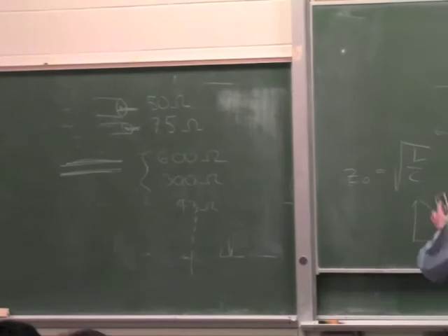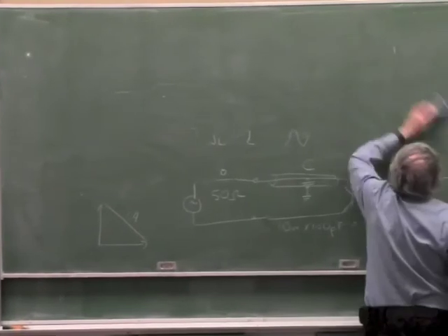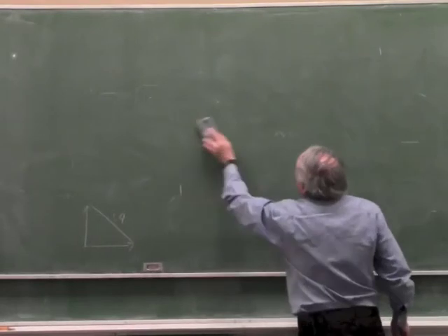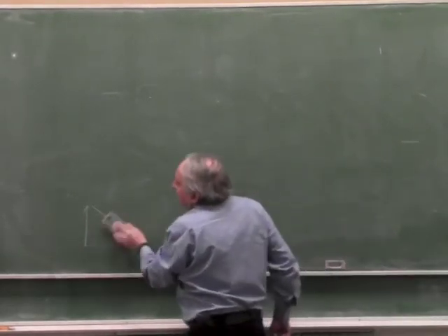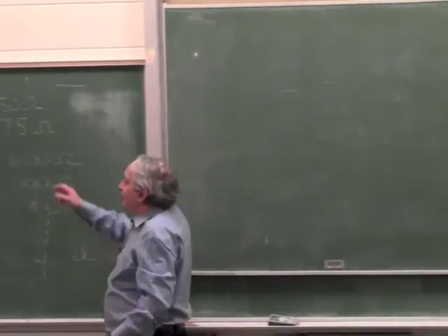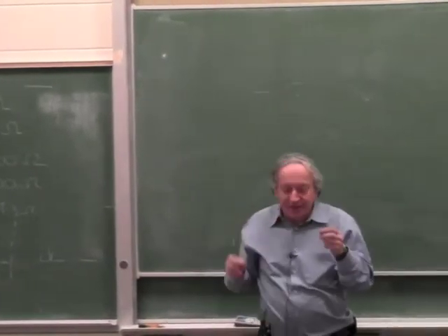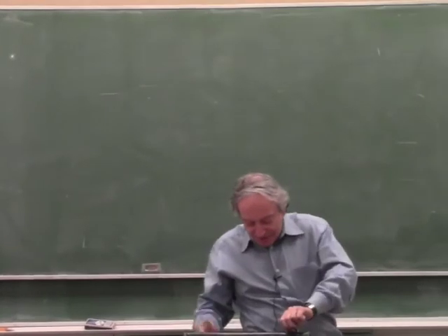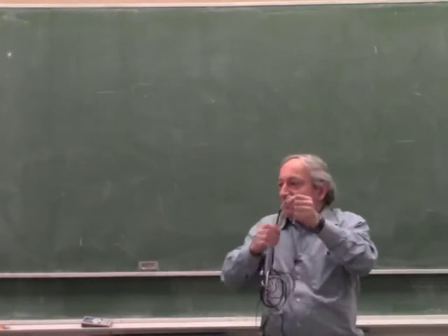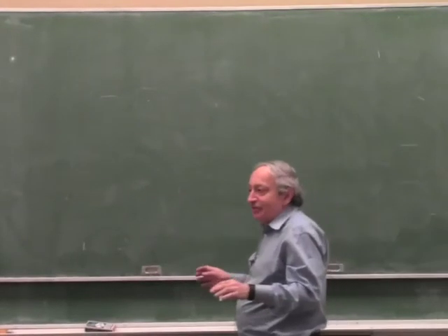Now, the second concept I explained last week, which is very, very important, is this concept of shielding: just because you put something in a metal box doesn't really mean it's completely shielded from electromagnetic interference, the same way that the shield around the wire, this braid I showed you surrounding the wire, doesn't protect it from everything. I showed you that in a shielded cable you have a metal braid, and I explained to you not to assume this metal braid stops all electromagnetic fields.